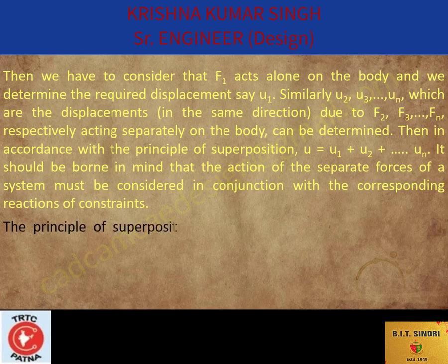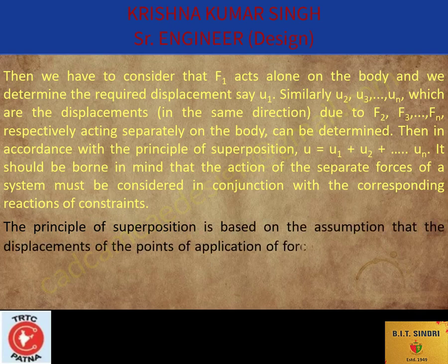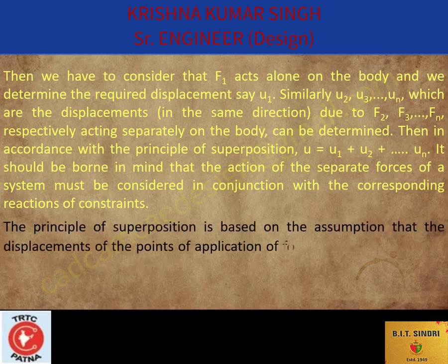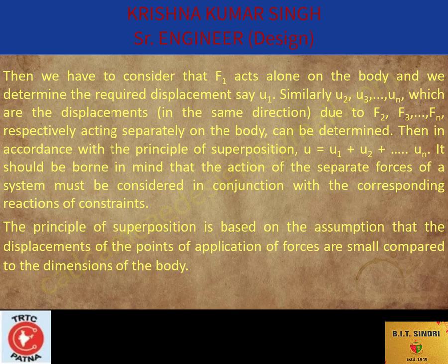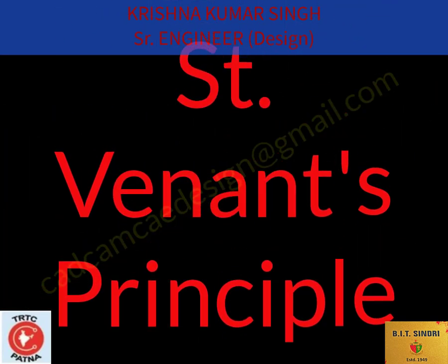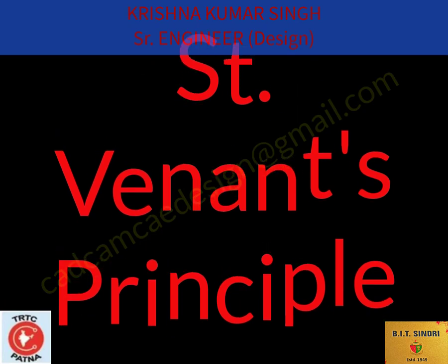It should be borne in mind that the action of the separate forces of a system must be considered in conjunction with the corresponding reactions of constraints. The principle of superposition is based on the assumption that the displacements of the points of application of forces are small compared to the dimensions of the body. So after the completion of the principle of superposition, the next topic is Saint-Venant's principle.